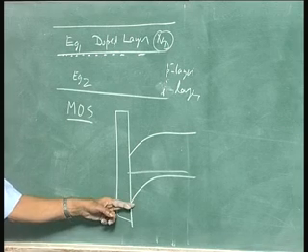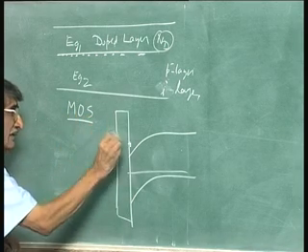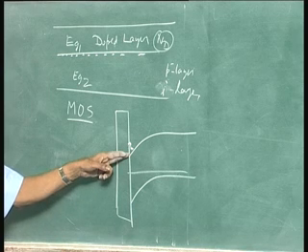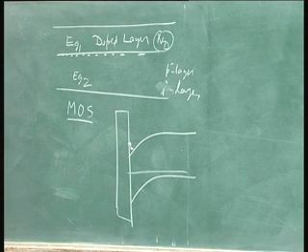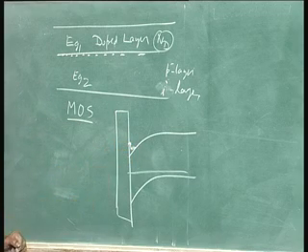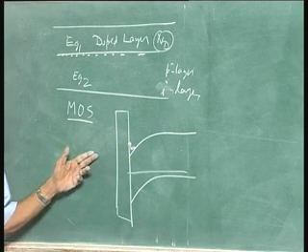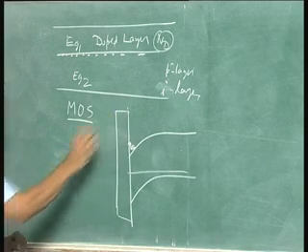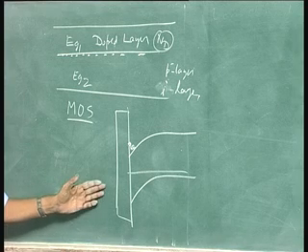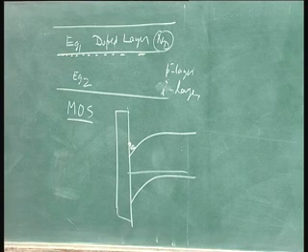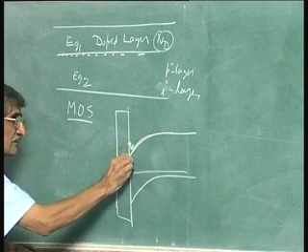Inverted region. Okay. You can see the electrons are locked here. You have a notch here. So, that is the inversion layer. Electrons somehow come here due to applied gate voltage, and they are locked here because they cannot climb up here. That is oxide. If you make a heterojunction, you will get a similar notch here.